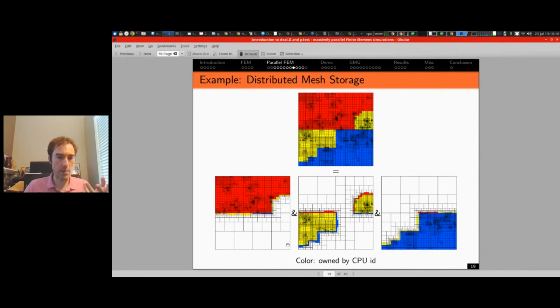So this is scalable. Because in deal.II we enforce 2-to-1 balance over the edges, there are these gray or white cells here that are artificial cells that are actually stored, but this is typically a small amount compared to the actual cells that we have. And we want this because we want to store the refinement starting from the coarse mesh that every processor has.